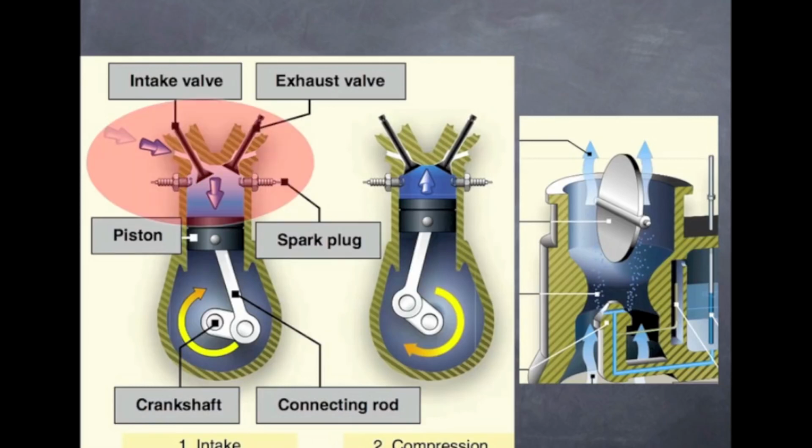So when the cylinder is moving, it's sucking air out of that manifold, creating a negative pressure within that manifold, a suction or negative pressure or a vacuum. When you begin to actually close the throttle, you're actually going to choke off the engine a little bit.